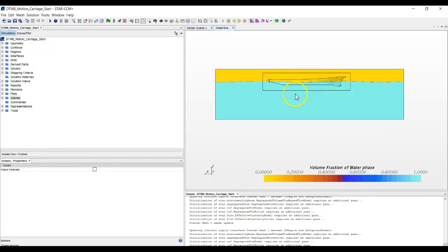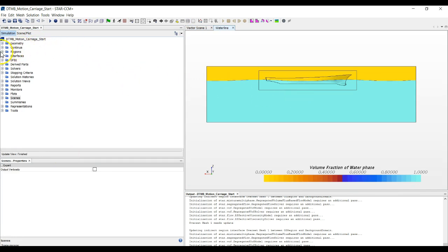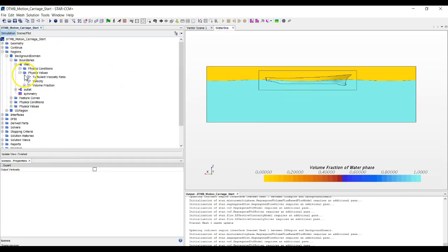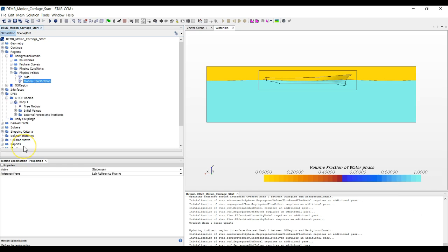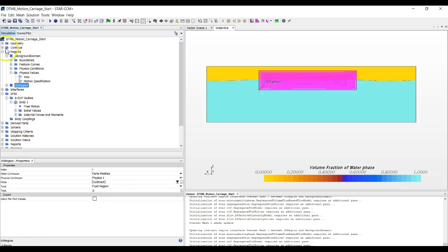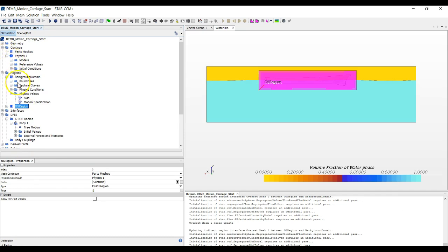An alternative approach we can use is to simulate the forward surge motion of the vessel whilst having the boundary conditions set to those of the wave we are modelling without the need for an additional or superposed velocity. This is a similar methodology to one of the two main options for simulating self-propulsion, in which the vessel is free to surge. To demonstrate this setup, we will start from a typical first order added resistance in wave simulation consisting of two regions with an overset mesh approach.